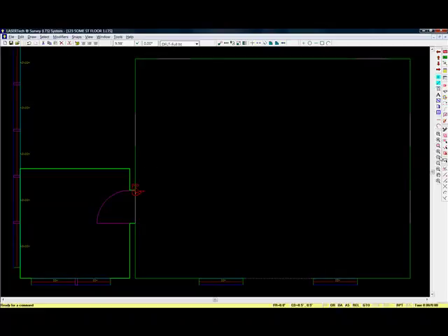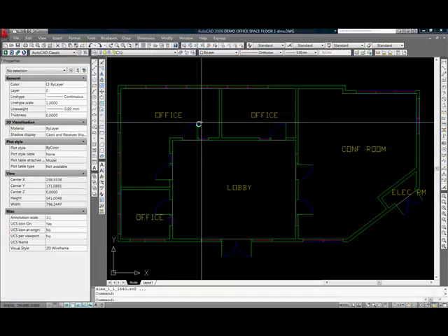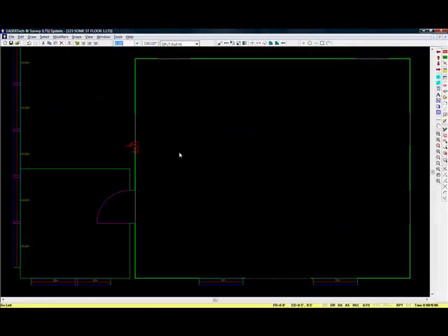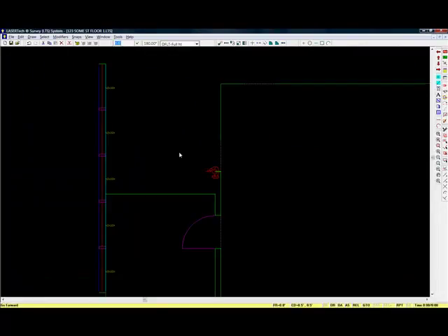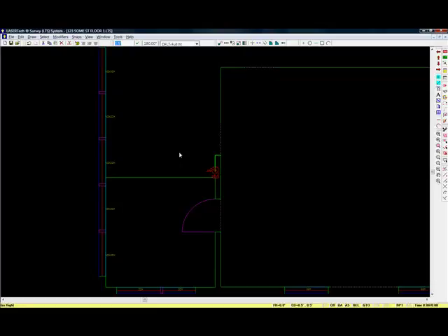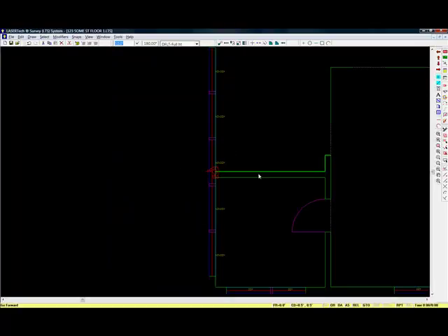Now the surveyor would next go into the next room, so he would go to this point and start laying out this office. So he would turn and go 0.5 feet, and then he would turn and go, it's about 1.5, and turns here and he goes 10 feet, and you can see we have a wall thickness, just by going in and measuring each room independently. The wall thickness is derived just by the fact we're measuring everything to 1/8 of an inch.